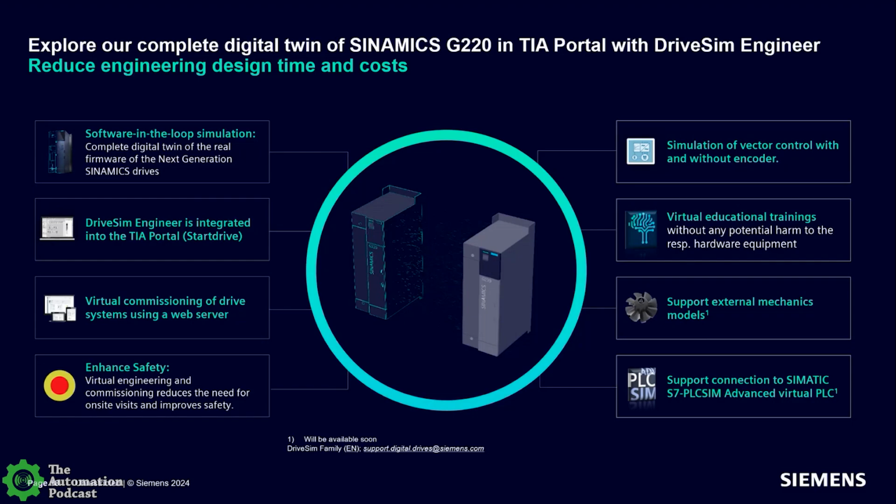The commissioning, or the way you configure the drive there, is directly transportable into TIA, or it's done in TIA Portal. So you can use that same configuration when you go to configure your product out on the factory floor. So you've configured it once, you've configured it virtually, but I can download that configuration to the actual product. So those are some of the things with regards to that digital twin.